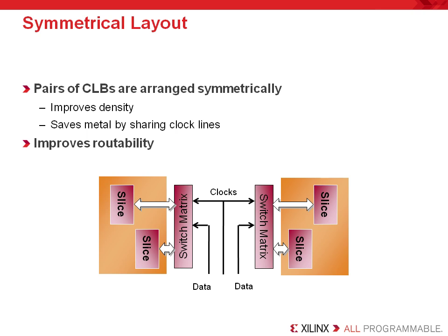In the end, how you actually get a hold of this is invisible to the user since the implementation tools will optimize the place and routing solution for you. And again, we don't encourage designers to ever have to go in and try and control this, since it should not ever be something the user has to control. The tools, again, do a very good job of managing the grouping of your logic into CLBs and managing the routing solution of the implementation tools.